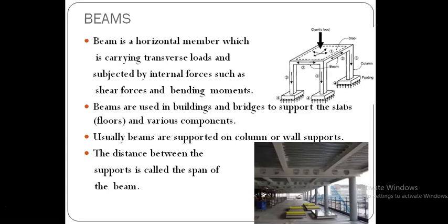Then the internal forces are developed. So those forces are nothing but bending moment and shear force. So any horizontal member which is subjected by transverse load, then it is having some internal forces such as shear force and bending moment. So that member is called as beam.